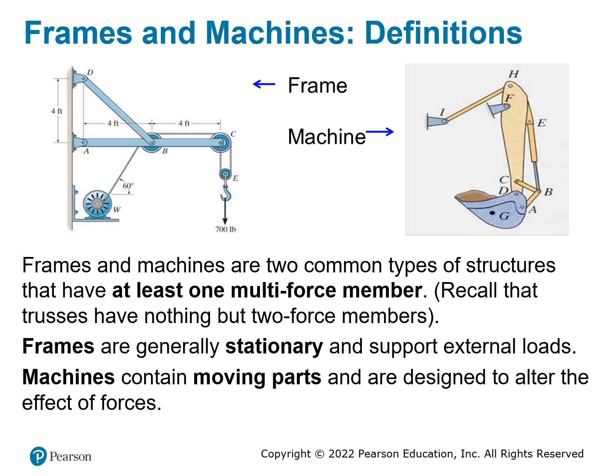Normally, if you have a frame, it is more like a stationary structure. The machine will have moving parts, but when we are doing the design, we don't treat the moving part as a moving object. We treat it as a static object. That's what we are doing here. We're doing a static analysis.